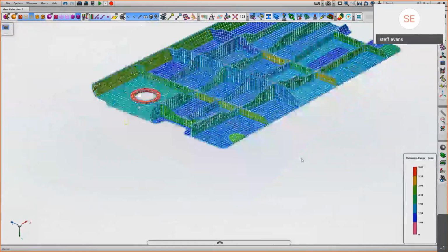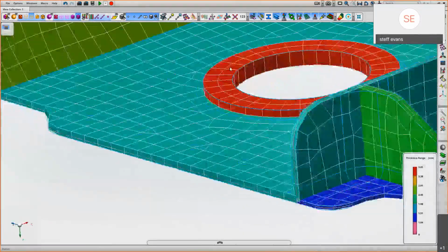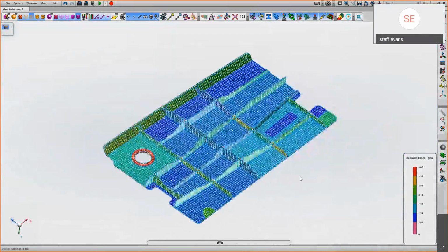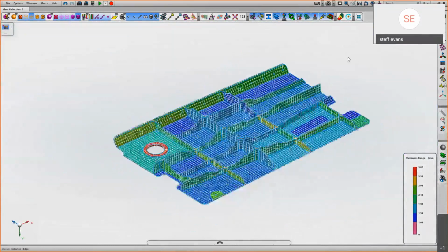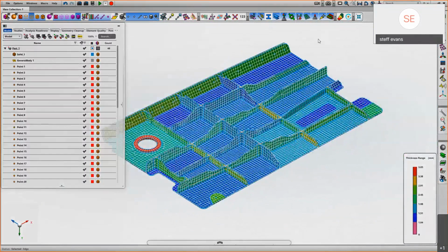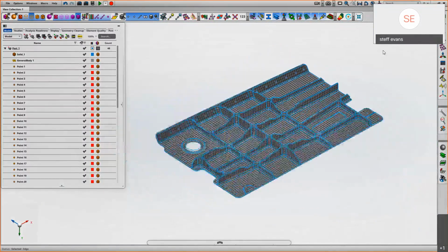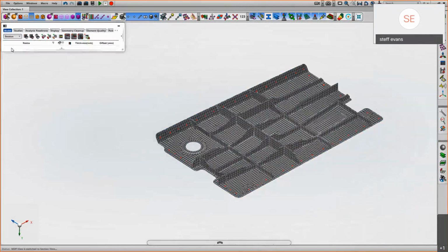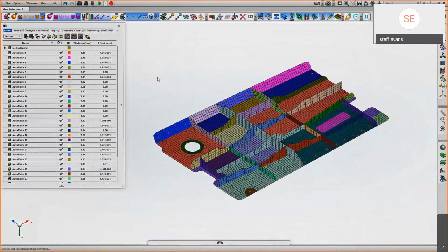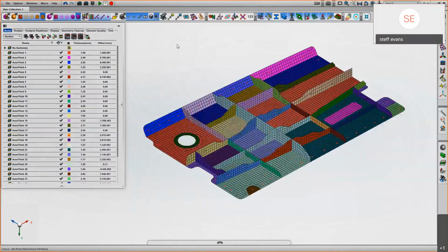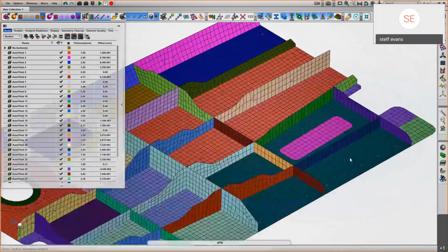Okay, I just want to show you the section view tool now, just to make clear sense of all these definitions. Some of you may be aware of this. This is something that I stumbled across, and it does make things a lot easier when you're mapping shell properties. So in the model browser, if you switch view to section view, this gives us a color-coded mapping of all the thicknesses that have been calculated from the underlying geometry.